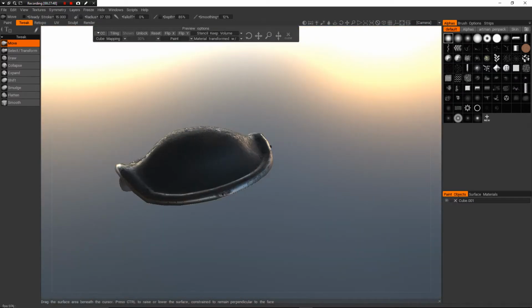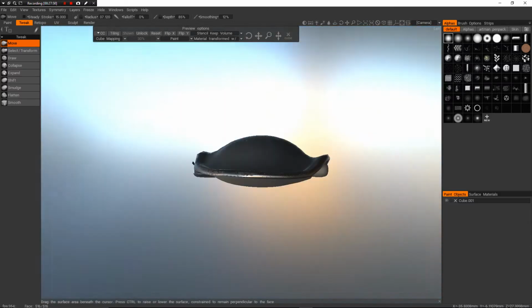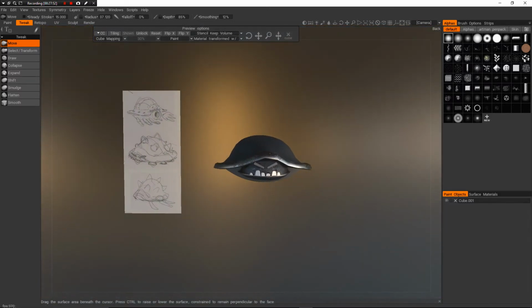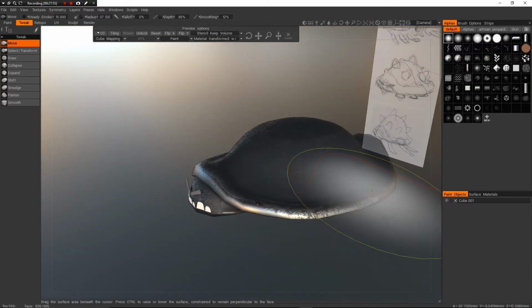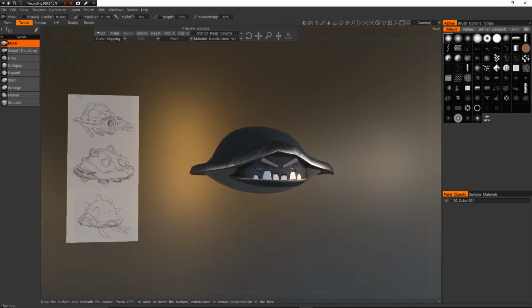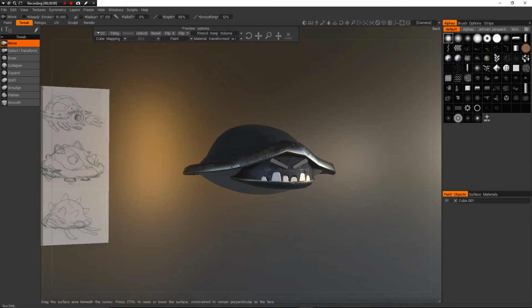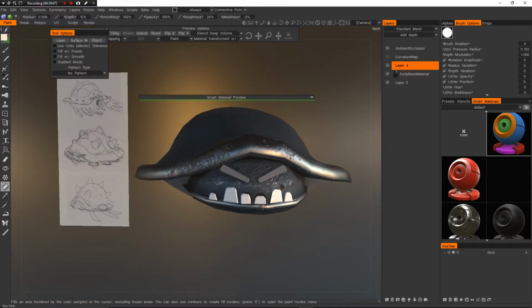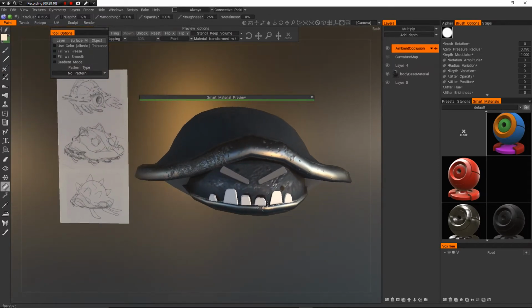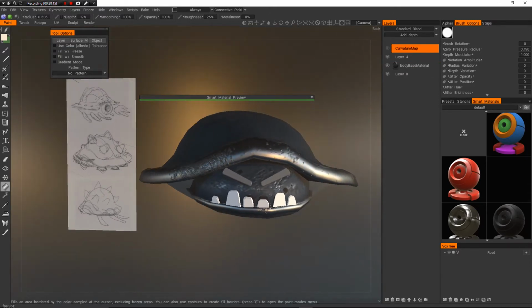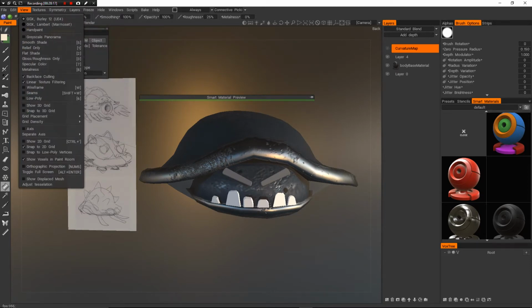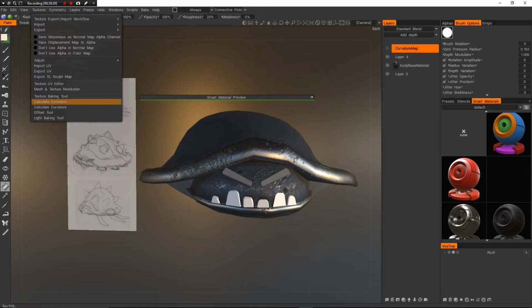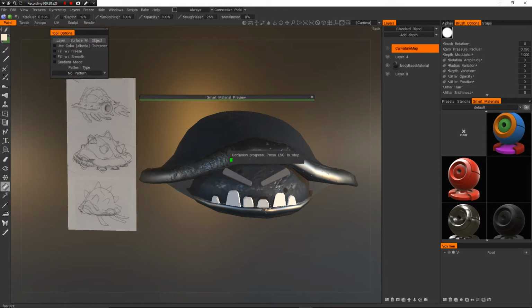All right. Cool. All right, so I'm happy with that. I probably want to get a nice lightness on this edge here. So let's go back and do some more painting. So back to my paint room. What I'm going to do, I'm going to rebake my ambient occlusion. So I'm just going to delete this. And I'm going to go to calculate occlusion. I'll just go OK again.